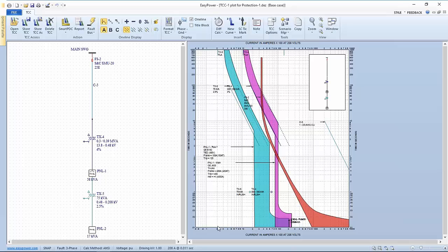If I have in this case, a 200 amp fault, and it lasts for hundreds of seconds, it also will not pick up any of the protective devices. Whereas if I have a current spike that's 37,000 amps, and it lasts for a second, any number of these protective devices is going to be activated, and so I'd expect to see systems drop off.